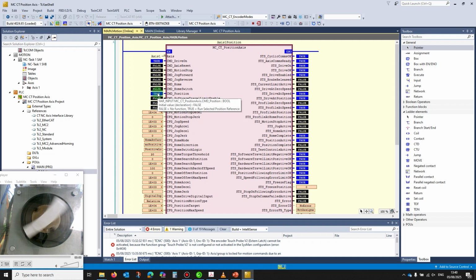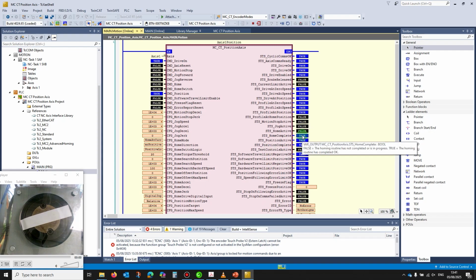So in a minute, the video will catch up. There you go. So that's moving on, doing the 10 revolutions, and then it will come to a stop. And there you go. We can see that position has become complete. Position is active. You can also see that even though the homing reference isn't on, a homing has been completed. So there's lots of nice status information over here.